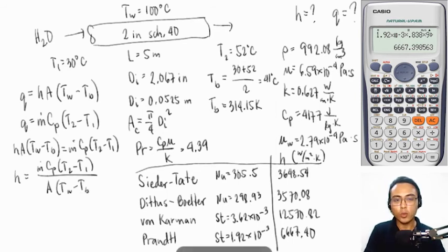Now, the question is, what area are we pertaining to in this instance? This area came from our equation of the overall heat transfer, Q is equal to HA delta T. If it comes from our overall heat transfer equation, that area is the surface area of transfer. And based on our system, the surface area of transfer is the inner surface area of the cylinder, that is pi dl. Let's solve for the value of the heat transfer coefficient.